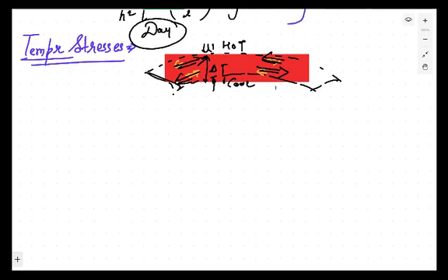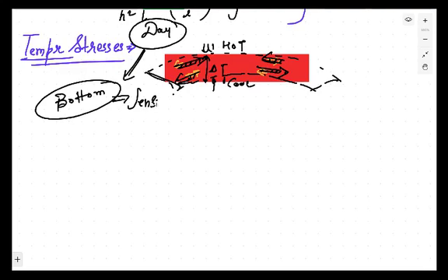That's why the subgrade will behave opposite to that of the slab. If the slab wants compressive stress in a certain region, then the subgrade will offer tensile stress in that region. It means that the final stresses present during the daytime will be compressive at the top and tensile at the bottom. So during the daytime, the bottom portion of the slab is critical, because in the bottom portion there is a presence of tensile stresses.